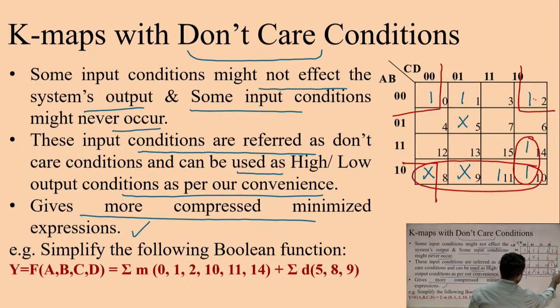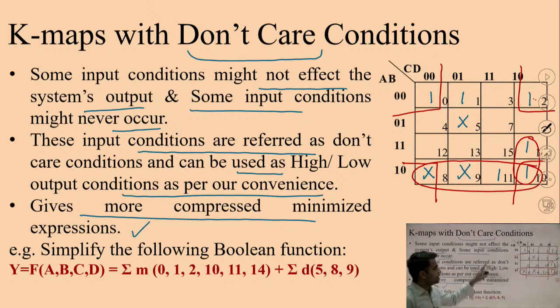So this can make a quad. Again, this quad is only possible if I had don't care on 8. If this 8 number don't care would not have been there, then this quad possibility would not have been there. Then the only thing I could have made is to merge this 2 with 0 and make a pair. And for this one I can make this pair.